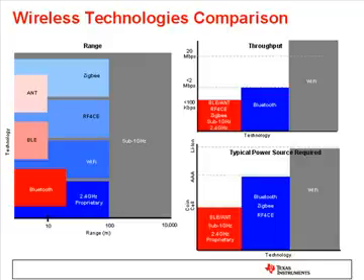From a power standpoint, as you can imagine, since Wi-Fi is the highest throughput, it will require the highest power. A misconception, though, is that Wi-Fi requires line power, but it can be battery-powered, in this case by lithium-ion. Bluetooth, however, can be powered by a AAA battery source, and then your BLE, ANT, and proprietary technologies will be possible to use a coin cell, so very low power there.